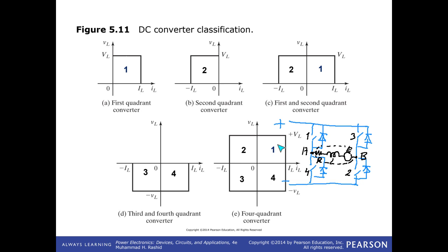Okay, so the first quadrant reflects the motoring case in positive rotation. Third quadrant is motoring but in reverse rotation. Second quadrant: the motor is rotating in the positive direction, therefore voltage is positive, and the voltage also reflects the back EMF, but current is negative. So it's actually a braking part. Power direction is negative, so you are braking your electric motor.